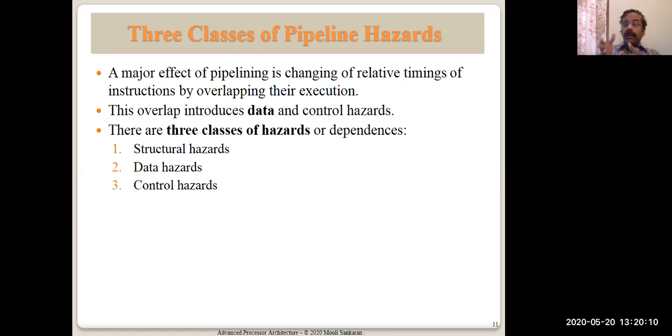Whereas if the instruction memory is corrupted and a wrong instruction opcode comes into the CPU, I don't expect the CPU to perform anything. But at least it should identify that it has read a wrong instruction and stop. It should raise an illegal instruction exception, so that the user will know that either the memory is bad or the compiled executable code is wrong, something has gone wrong that the CPU is not able to handle.